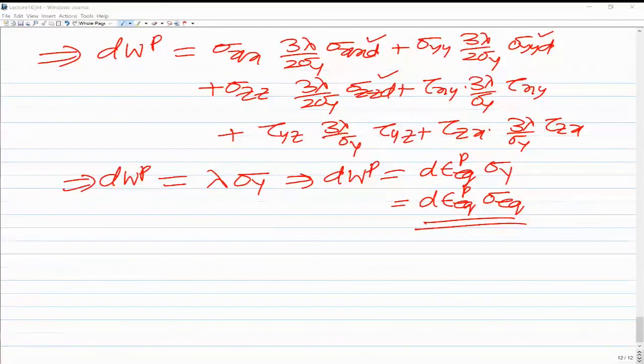So in that case, for each element you are using a local xy coordinate with origin at the bottom left node, that you are taking as origin. As long as you do that, the element level governing equation for all the elements would be the same, provided other properties are independent of xy.